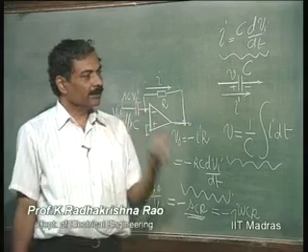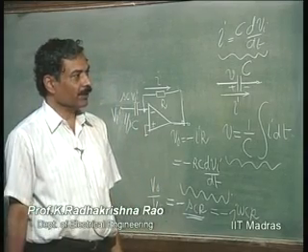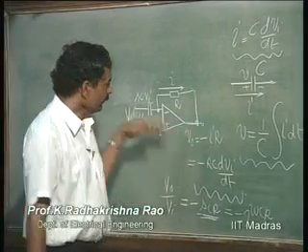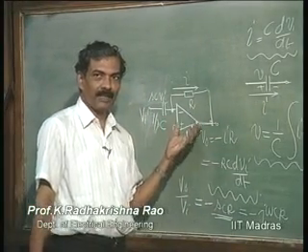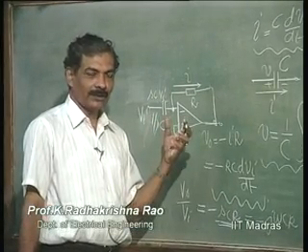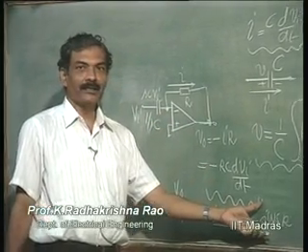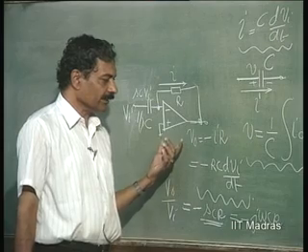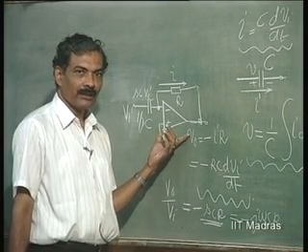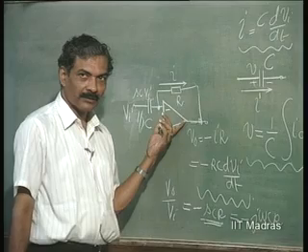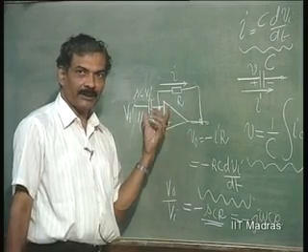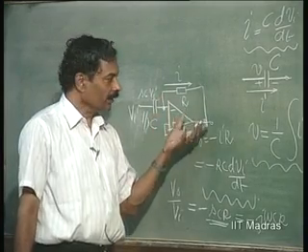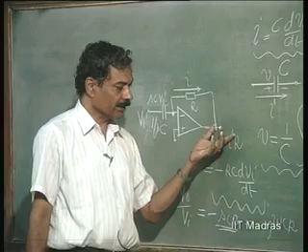If there is a voltage induced because of somebody starting a scooter or car or anything, that will disturb this differentiator, because that will appear at the input as an induced voltage, and that will be amplified considerably by the differentiator. So, normally differentiators like this are not used because they are amenable to noise. The output is disturbed by sudden fluctuations of voltage which can be picked up, and that will be amplified at the output considerably.